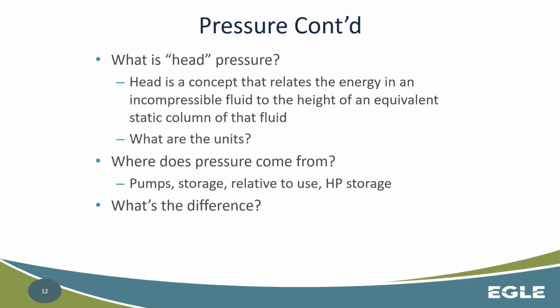Now, what is head pressure? Head pressure is a concept that relates energy in an incompressible fluid to the height of an equivalent static column of that fluid, right? So what that means is if I tap into a distribution pipeline with a tube and I'm extending that tube up into the atmosphere, I can measure the pressure in the pipe with how high the water level rises in that tube.